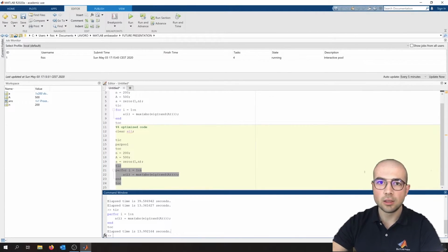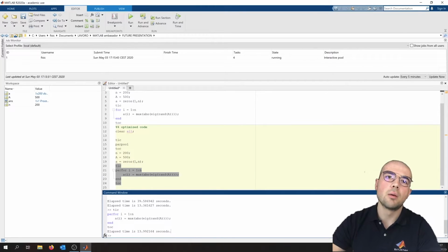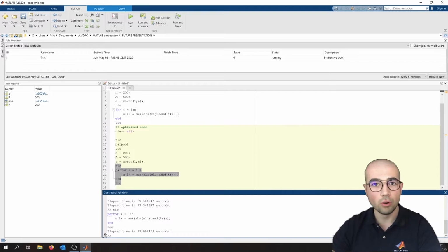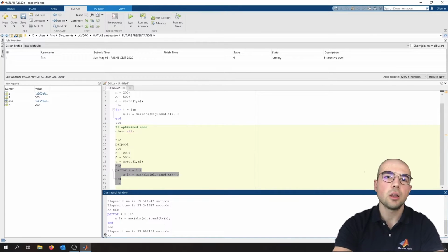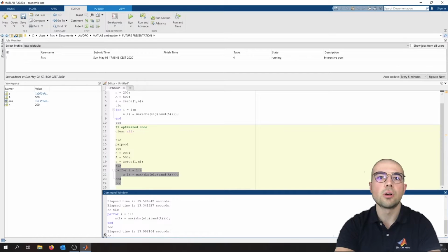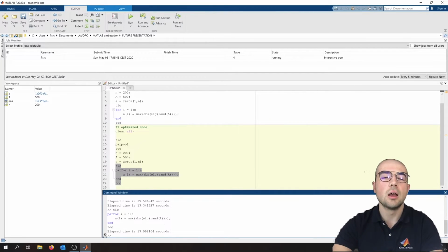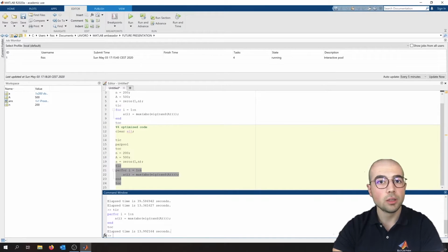Perfect. The last thing I have to mention about parpool parallelization is that if you want to run this type of command on your PC, you have to consider that it is quite hardware intensive. So you must have at least a multicore processor on which each core can become a worker. Second, you also need some gigs of RAM. In particular, you need at least 2 gigs for each worker if you are using a MATLAB operation, and at least 4 gigs per worker if you are using Simulink parallelization.